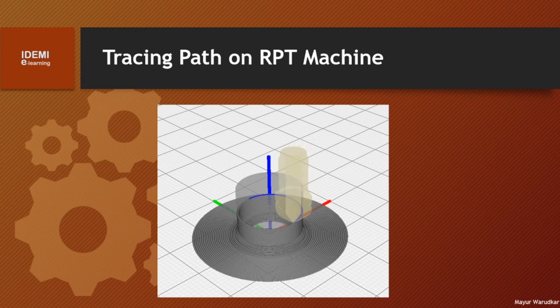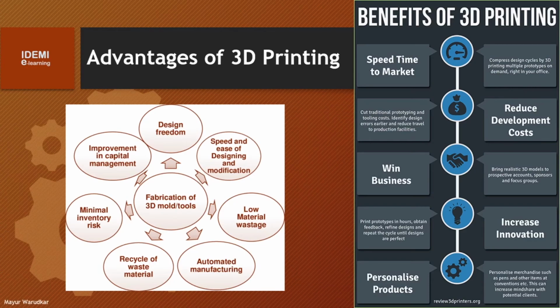What are the advantages of using additive manufacturing? Similar to standard 3D printing, additive manufacturing allows for the creation of bespoke parts with complex geometries and little wastage. Ideal for rapid prototyping, the digital process means that design alterations can be done quickly and efficiently during the manufacturing process. The lack of material wastage provides cost reduction for high-value parts, while also having been shown to reduce lead times. In addition, parts that previously required assembly from multiple pieces can be fabricated as a single object, which can provide improved strength and durability.